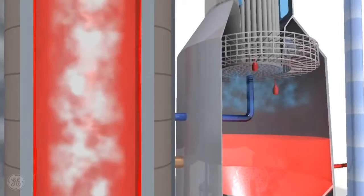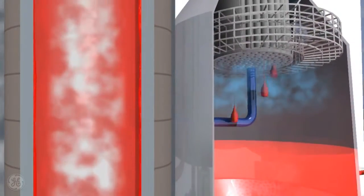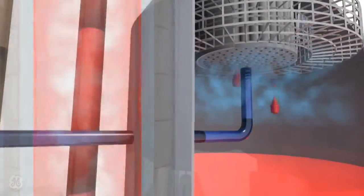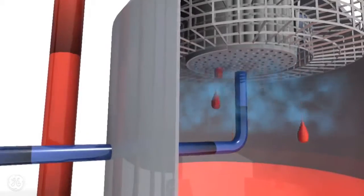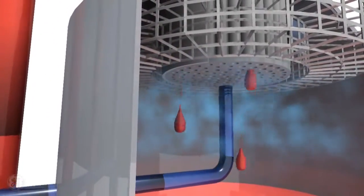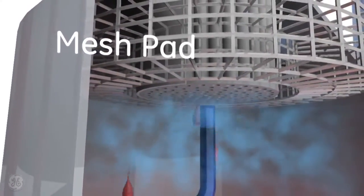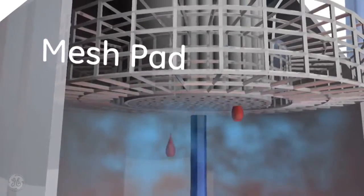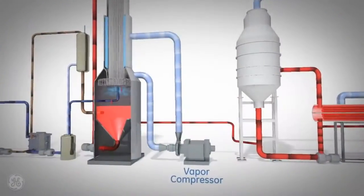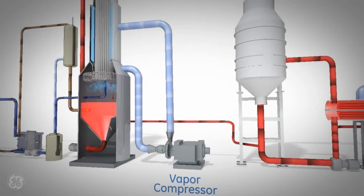For the brine that reaches the sump as liquid, it recombines with the brine already in the sump, as well as new feed brine coming into the sump from the deaerator. That mixed volume will then recirculate back to the top of the tube and shell. Evaporated water vapor flows through the mesh pad mist eliminators. The mesh pad mist eliminators remove any brine droplets from the vapor. That vapor exiting the mist eliminators flows to the vapor compressor.